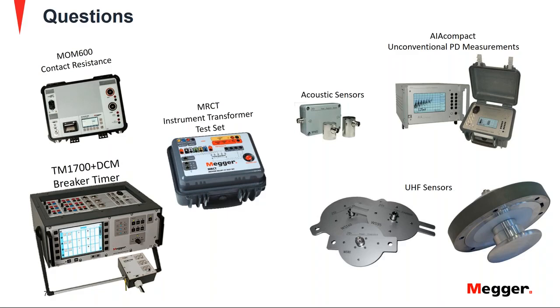All right, thanks, Daniel. Volney, can DCM detect main contact bounces? Yes, this is a very minor detail that you get when testing the timing of the main contacts of a breaker, but it's a very important detail to measure. The fixed contact could be loose, and it may cause temporary disconnections of the main contact while the breaker is operating, and they are common to see, but you don't want to have many of those bounces. The conventional timing of a breaker detects these bounces, and DCM does as well.